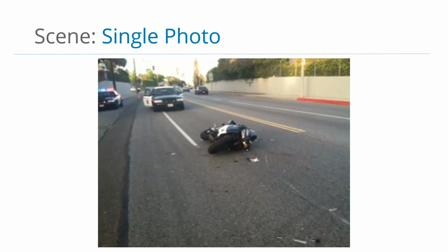to determine the final rest of this motorcycle, the actual location of the gouges that lead to the final rest of the motorcycle, how long the gouges were, maybe you're interested in where the debris is. It is possible to map all of this evidence using just this photograph, well, in most cases anyway, as long as some of this background context still exists. If the roadway hasn't been repaved or there's not some sort of major construction that's gone on between the time of the accident and the time of your investigation.